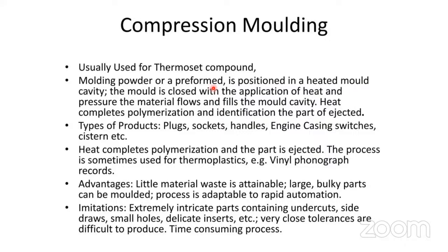Second thing, we can add the accurate material, maybe 4 tablets per shot, maybe 6 tablets per shot. Therefore, there is no wastage of material. And that's why we are using a preform, that is a tablet or maybe tube type shape preform. We are converting, I told you, the powder into the preform.